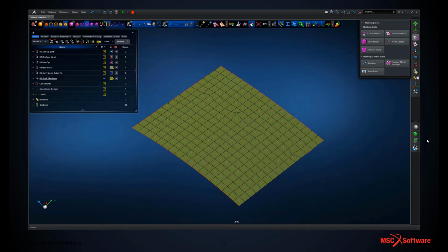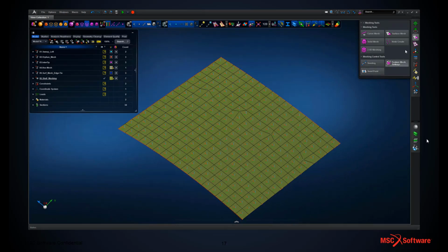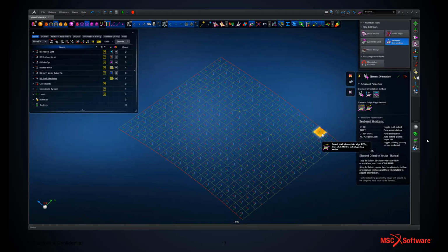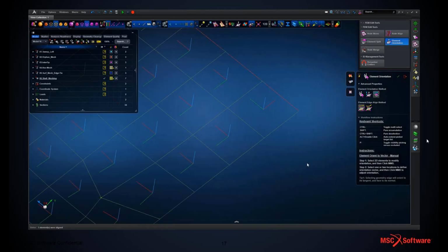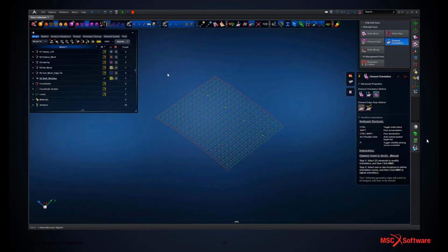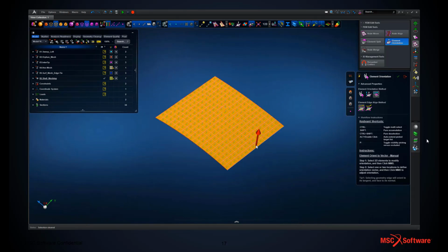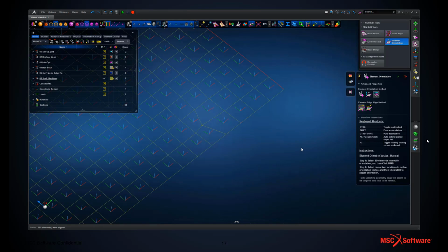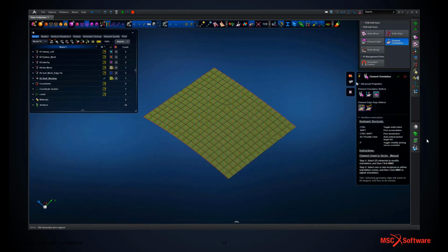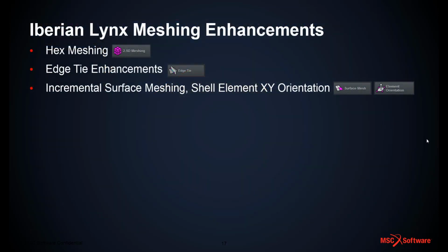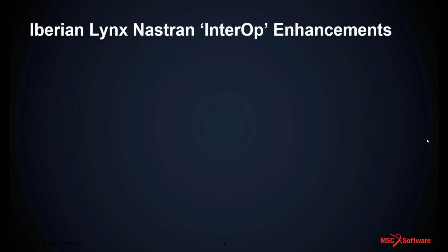One thing which is very important in an aerospace environment, especially if there's going to be downstream hand calcs, is to ensure element alignment for a given region. So we've got shell elements here with the x-axis originally pointing parallel with the long edge. We're changing those now so they're all pointing parallel with the shorter edge, so just a simple rotation of those element XY orientations to make sure we've got element consistency or result consistency in those XY directions.